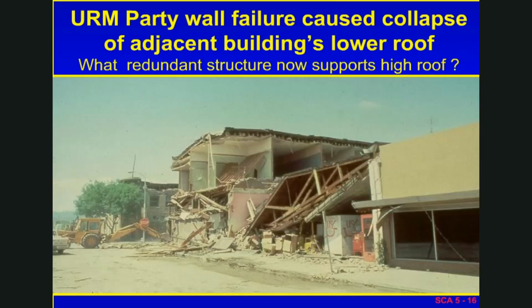So looking back to this building from Kalinga, it is really a good study of two buildings. One, the one on the corner, where you see the fact that the property line wall has collapsed and caused the building with the truss to collapse into what we would call an A-frame, or excuse me, that's a lean-to collapse. But the roof of the building on the corner hasn't collapsed because little catenaries have been formed. The redundancy of just having the plaster ceiling has held up that very light roof, of course. So there's lots of survivable spaces in that corner building, as you can see here in the lower picture.